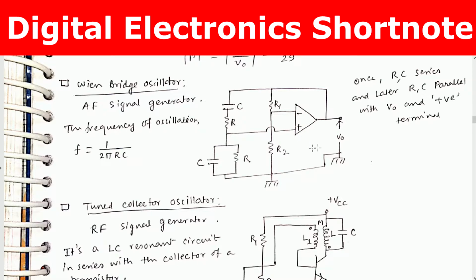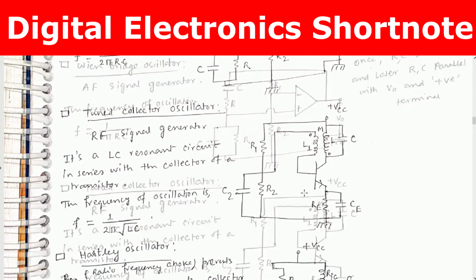Wien bridge oscillator. This is the Wien bridge oscillator, with R1 and R2 as a voltage divider, first RC series and then RC parallel, with V0 going to the positive terminal. So this I have written to remember. And this is basically an audio frequency signal generator. The frequency of oscillation is given by F equals 1 by 2 pi RC.